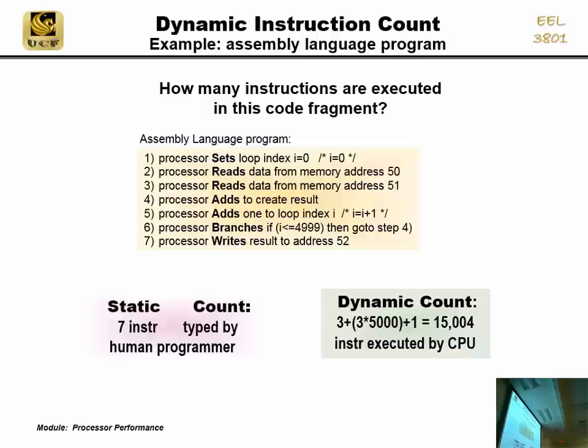You can add up and work with fractions of a second times 10 to the minus 9 and add these all up, or you can just add up how many clock cycles each one takes, if that's what's given in the table, get the total number of clocks for the program, and then just convert to seconds once. So if someone wants you to find the execution time for a program, sometimes it's easier to work with clocks rather than seconds, even though they're measures of time.